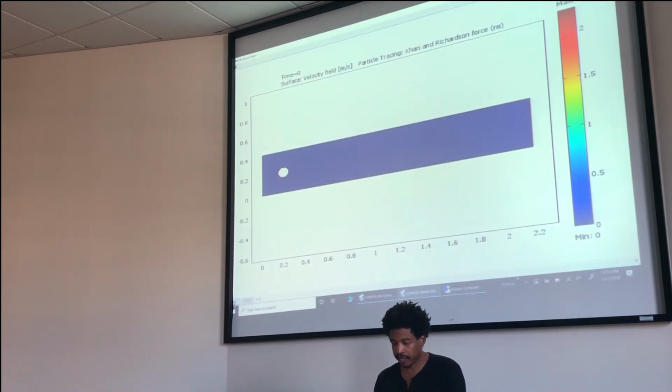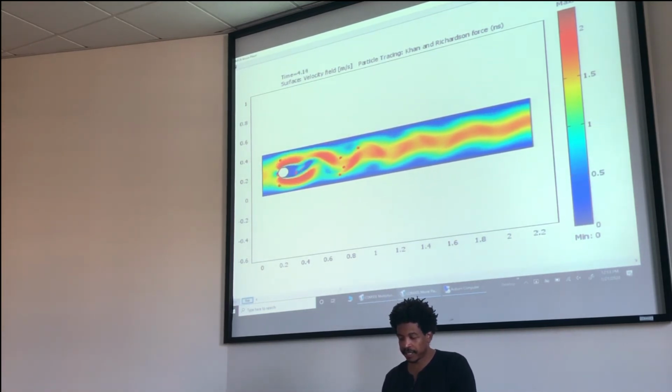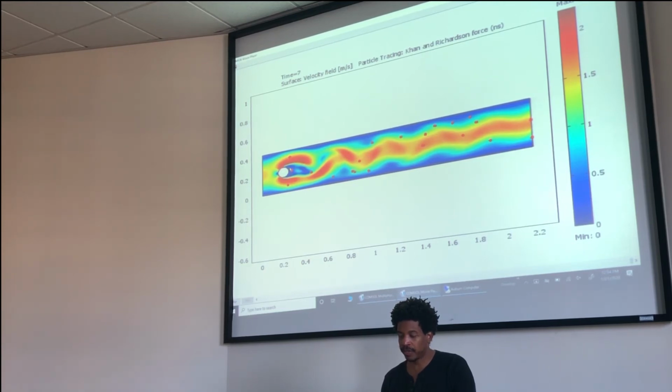It's an AVI, but it's low resolution. I should turn the resolution up. But this was happening right here. Those are the particulates coming out to do tracing. As you can see, if they get caught in blue, that's low velocity. If they get caught in the red, it's a higher velocity. This one is getting very close to the wall, so they're slowing down, because remember, there's no slip on the wall, so it's really 0 velocity if they get there. So very low velocity behind this little obstacle, very low velocity at the wall. So that's what that's all about.